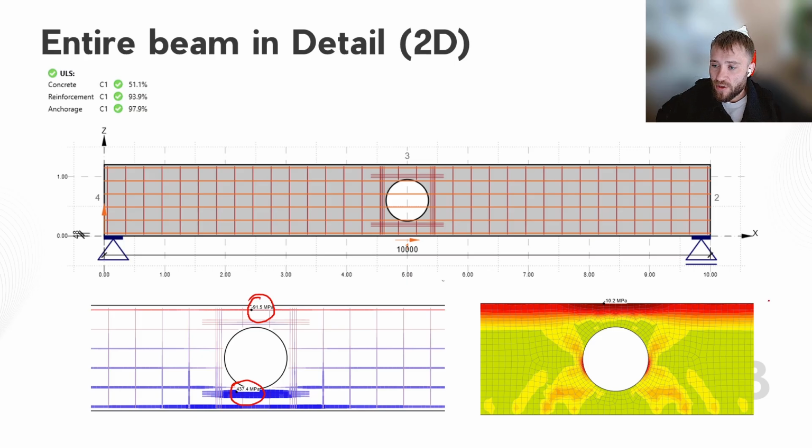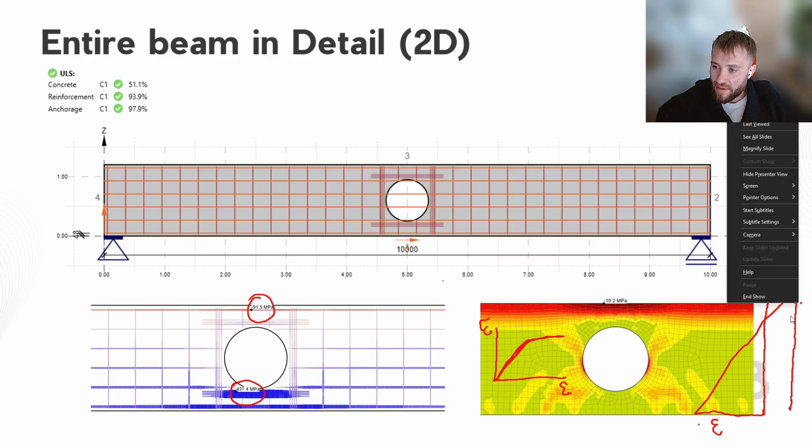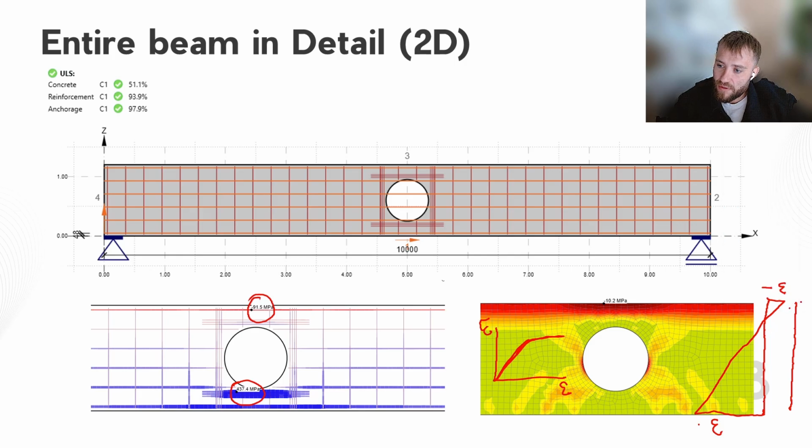And as we can see, if I just draw the plane of the strain, you're able to see this is my plane of the strain. Here is the compression, and here is the tension. And because we support the diagram that basically you know exactly from the Eurocode, here is the sigma and here is the epsilon. So this is the level, because we are on the 10 megapascal, so maybe we are still on the linear part. So I will just put it here.